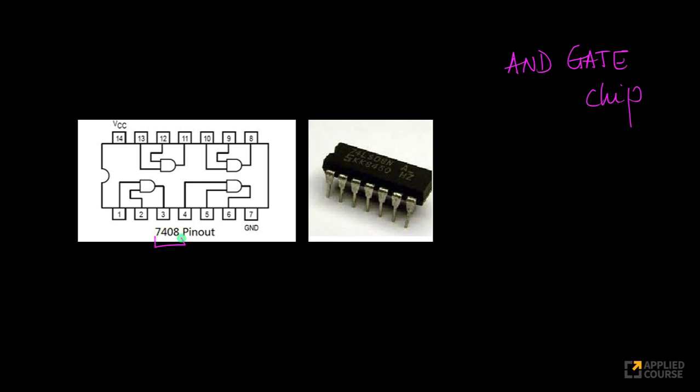Again, every chip has a unique number associated with it. So this chip number 7408 looks like this. Look at this. 74. This LS and all talks about some technology they are using, but effectively this is 7408. It's a small chip. It costs, I think, 10 or 15 rupees, or about 20 cents in US dollars. It's a very simple chip, and these are called pins of the chip. The actual physical logic itself is inside this chip. You can put this on a breadboard.